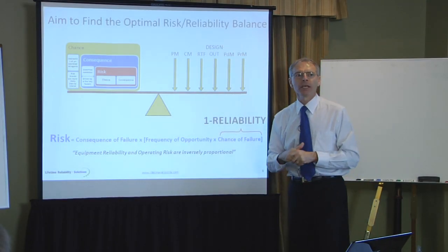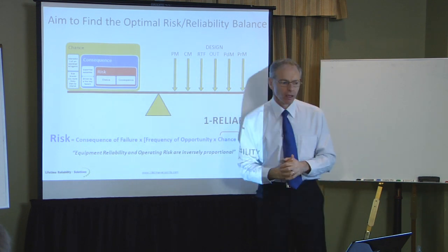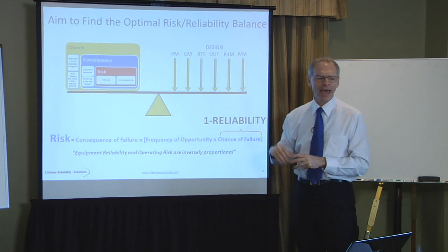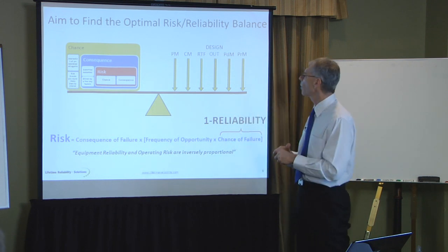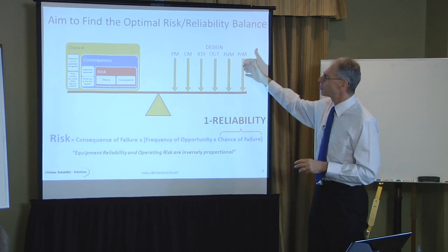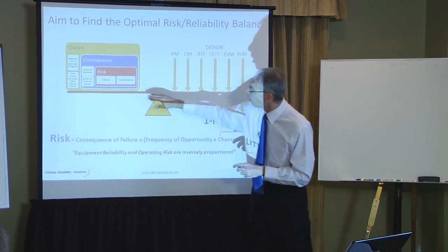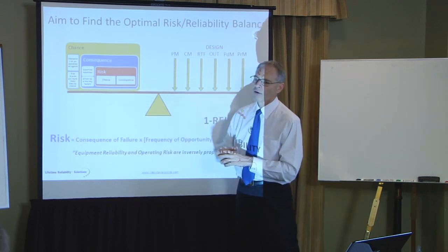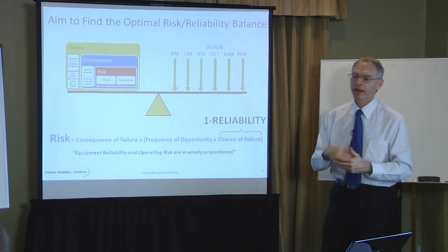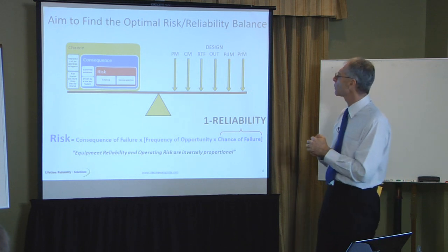Now, if the issue is poor material selection, if the issue is poor process control, then let's re-engineer that and solve that problem once and for all. PDM is predictive maintenance. So condition monitoring is going to be used to monitor the evidence of something going wrong. Because if I can detect the P point early before it becomes a disaster, then I can do planned maintenance at lower cost.